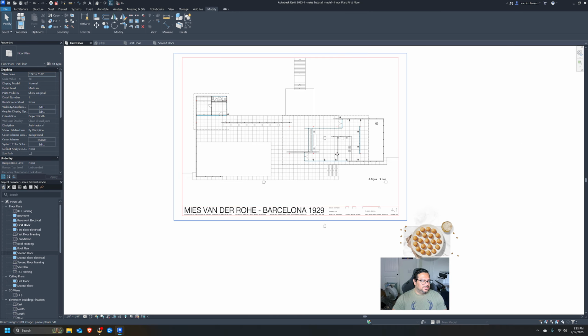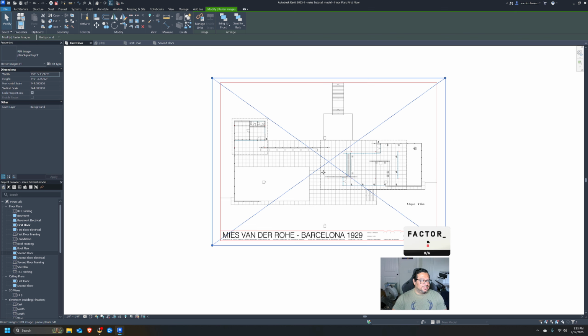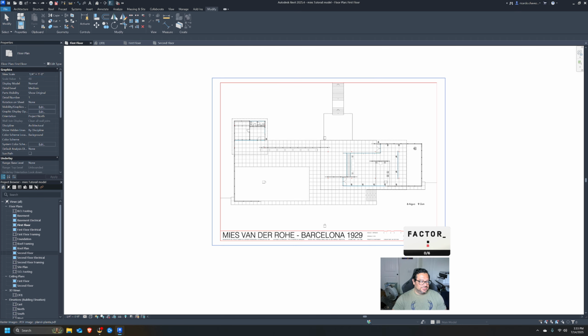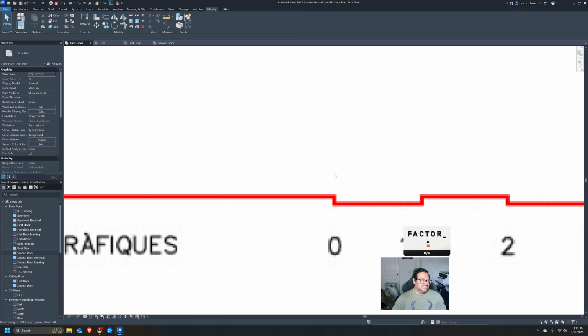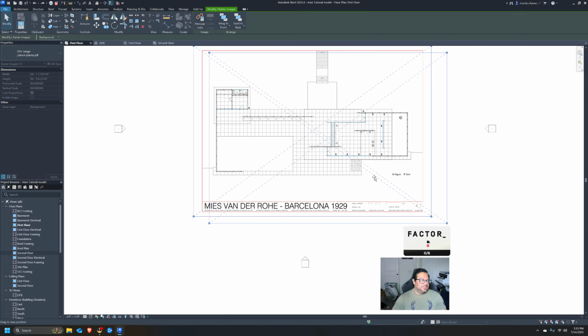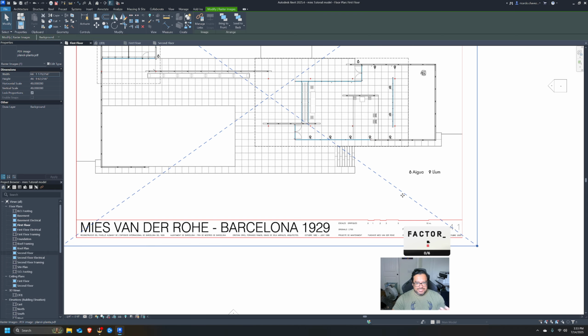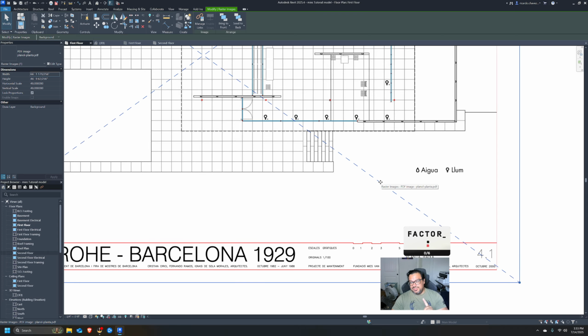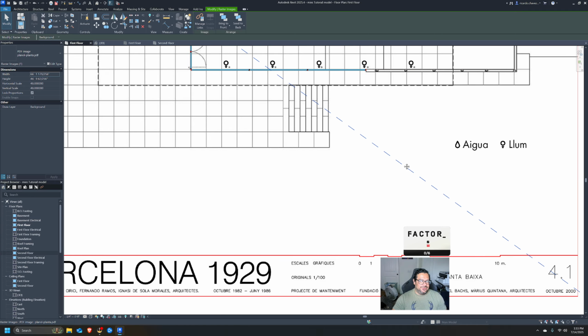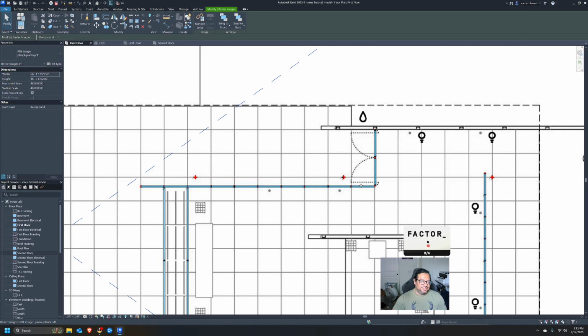I'll move it to the middle because we have the elevation tabs there. Once you get it scaled, we'll do it again one more time so you guys see. So this is our drawing, and we're going to scale it. But you're not limited to just that. Say you know that a door is 6 feet.